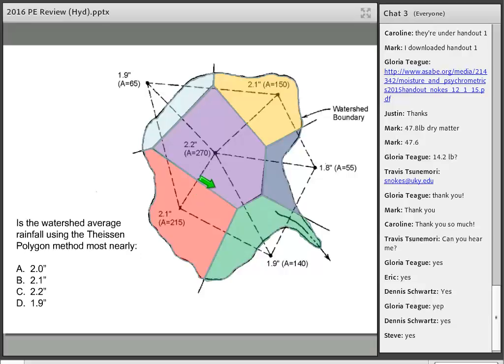So essentially what you end up with then is you've got these nice polygons, which I have colored a uniform color. The rain gauge that is within it is the closest rain gauge to that area. In the case of this 1.9 rain gauge that's up in the upper left, that's outside the watershed, this small light blue area is the area within the watershed for which that rain gauge that read 1.9 is the closest. Similarly, way over here on the one on the east, the 1.8, this kind of medium blue is the area that's closest to it rather than to one of the ones inside.